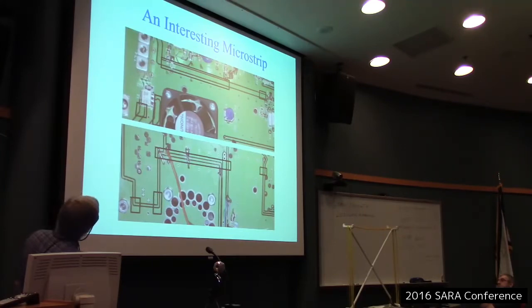Well, here I've got this trace running along here that's coupling things from the LO and the IF ports right to the RF port of the mixer. So all that carefully built isolation was destroyed by a poor printed circuit layout. So if something like a Mini-Circuits part doesn't work right, check your own layout first. It could be your ailment.